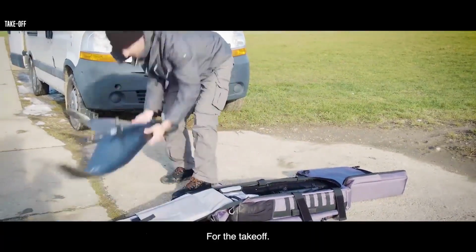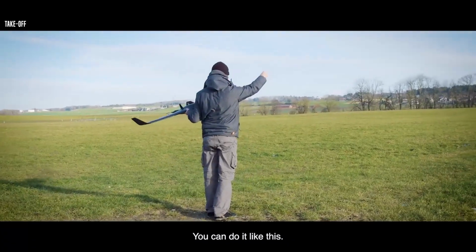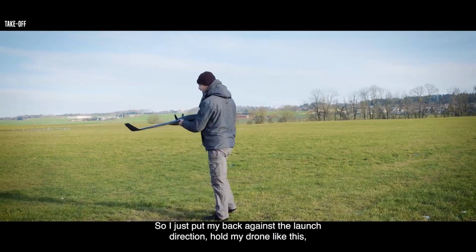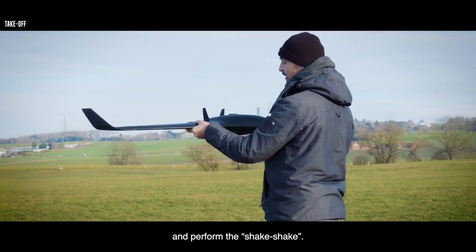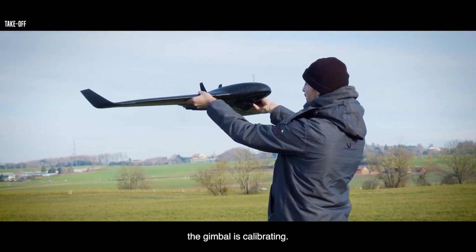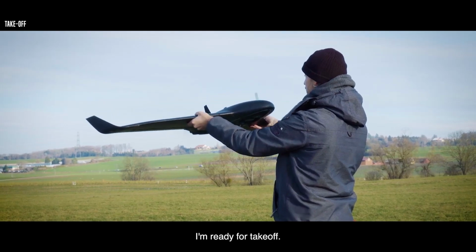For the takeoff, the first thing is just to check the wind direction. So you just do like this. So the wind is coming from here. So I'm going to launch in that direction. I put my back against the launch direction, hold my drone like this, and perform the shake. Here I make sure the control surfaces are moving. The gimbal is calibrating. And once the calibration is over, I'm ready for takeoff.